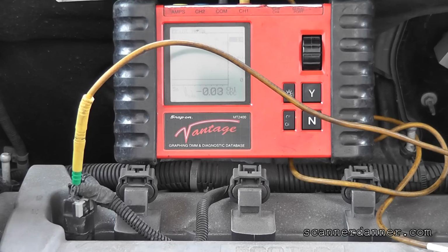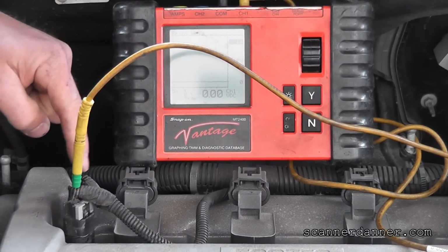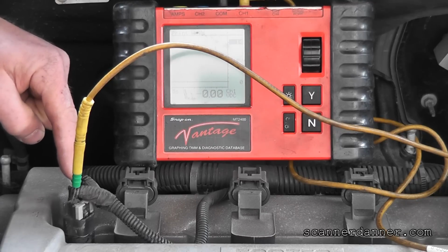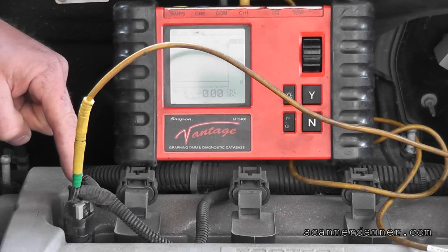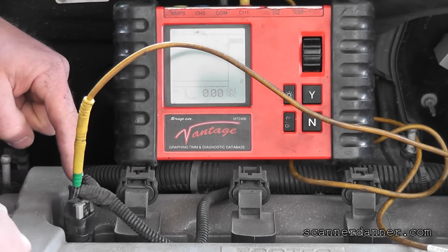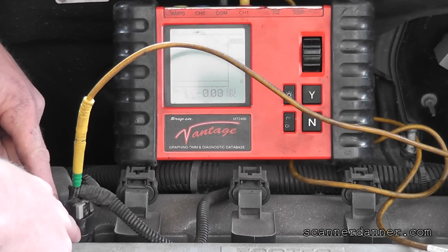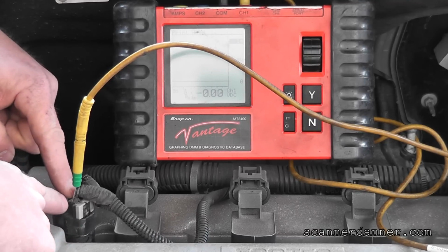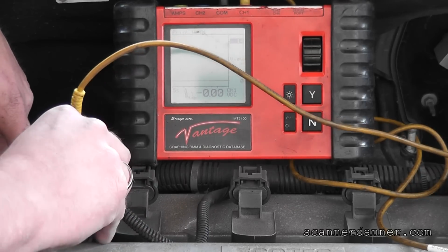So what that's telling me, before I really go any further, is this exhaust solenoid is open. That 0.93 that you're reading is a bias voltage, and I believe I can prove that. If I unplug this intake solenoid and create an open, I believe what you'll see is that the positive control wire is going to go high.